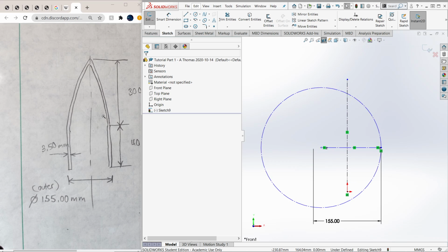So now I'm going to try to give the dimension from here to this line. And if you noticed, I can't actually click on anything in there because these are just lines. So you can use a point, and it's pretty useful to just stick points everywhere, and they won't actually affect the feature that you make, but you can use them to align things.